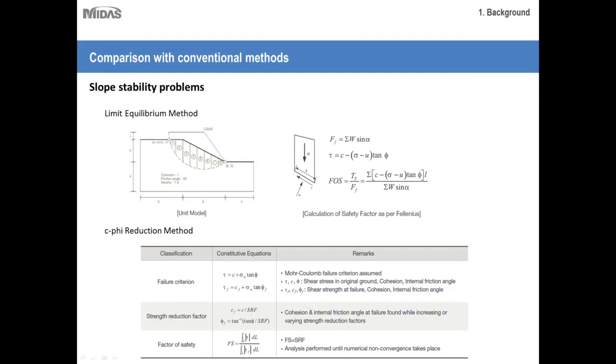So this is especially useful for simple slopes, or slopes that have very simple geometry. But one of the shortcomings of this method is that for slopes that have complex 3D geometry, it would require the use of something more sophisticated. That's where numerical modeling comes in.